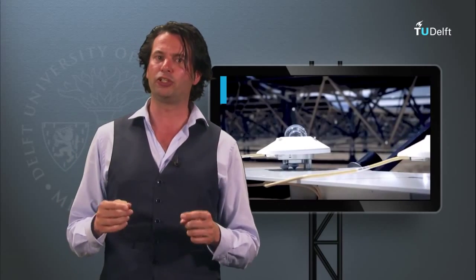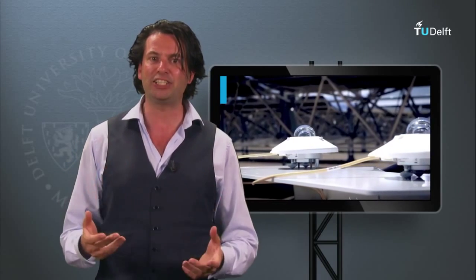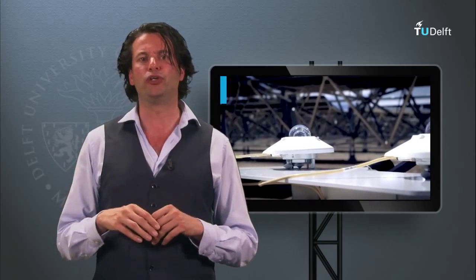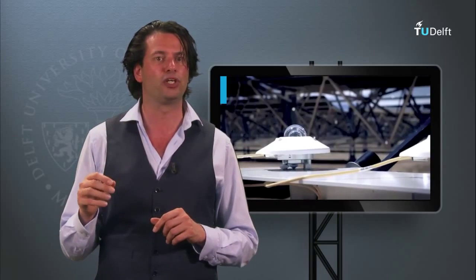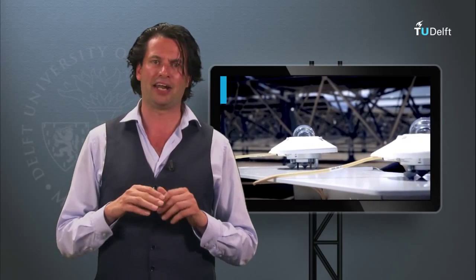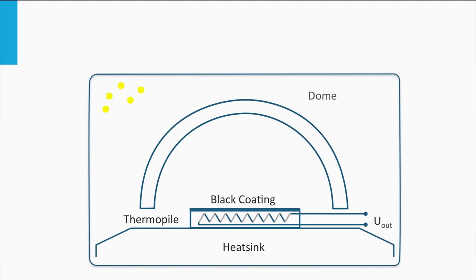These are instruments used to measure the heating power of radiation. A pyranometer has a field of view equal to the complete hemisphere and is sensitive to the full spectrum of solar radiation in the range from 300 nanometers to 3000 nanometers, and has a flat spectral response in the whole range. It allows us to measure the radiation very precisely, independent of the wavelength of light. It measures the thermal effect of the radiation.